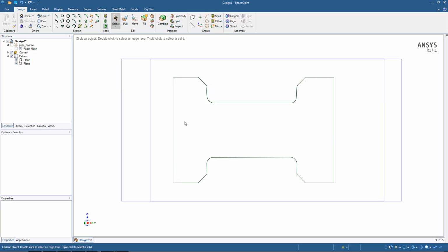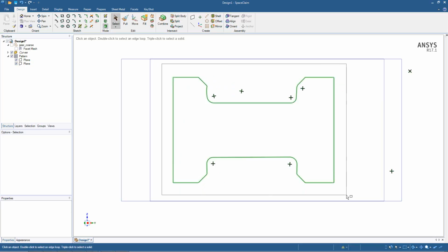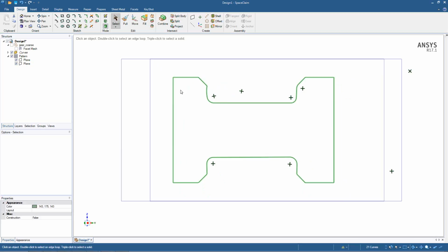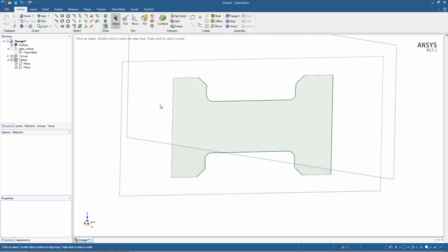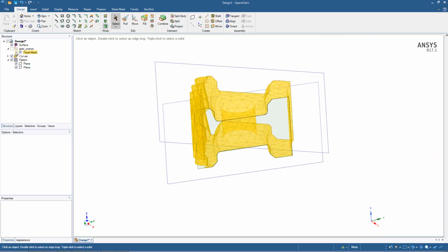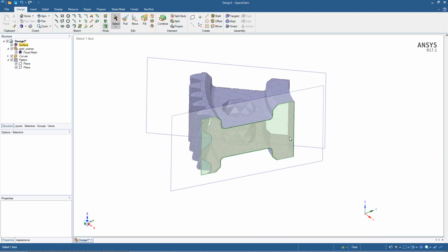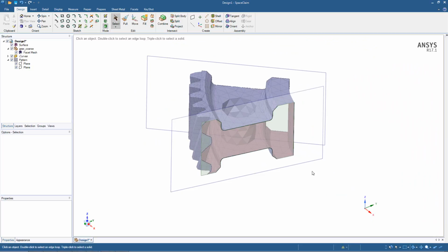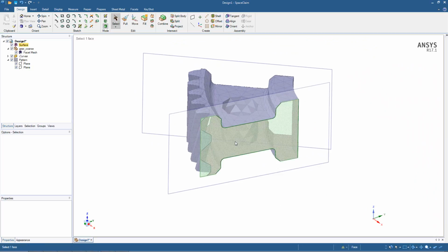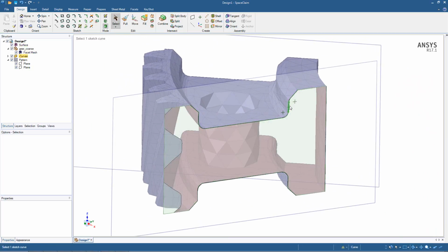profile. So then lastly, if we want to create a surface from all of these edges, these edge loops that enclose the surface, we can use fill again on that, and that will create a surface. So now we have the 3D surface that we were looking for that represents the cross section of this gear that will eventually revolve around. So we have that feature, again by using the STL file as a guide to build this surface.